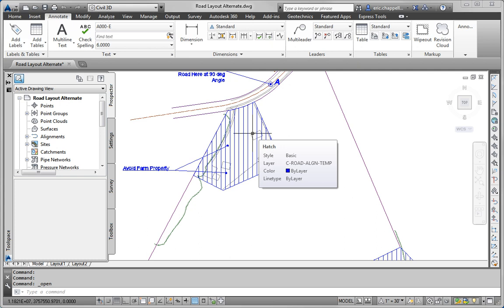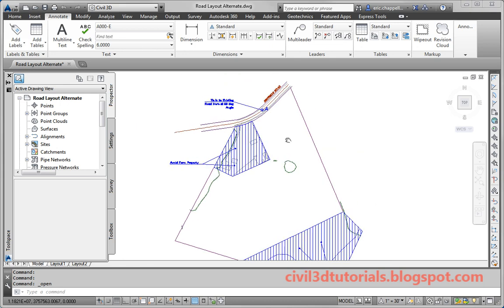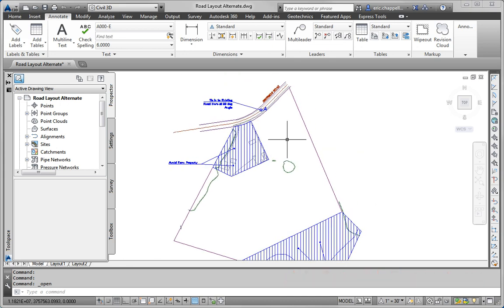So I'm going to look at this 2 ways. In the first way, I'm going to establish my constraints and then draw within those constraints. And then the second way is going to be a little more freeform. So we know that we have a 150 foot offset from the road center line to the backs of the lot. So let's reverse engineer that.